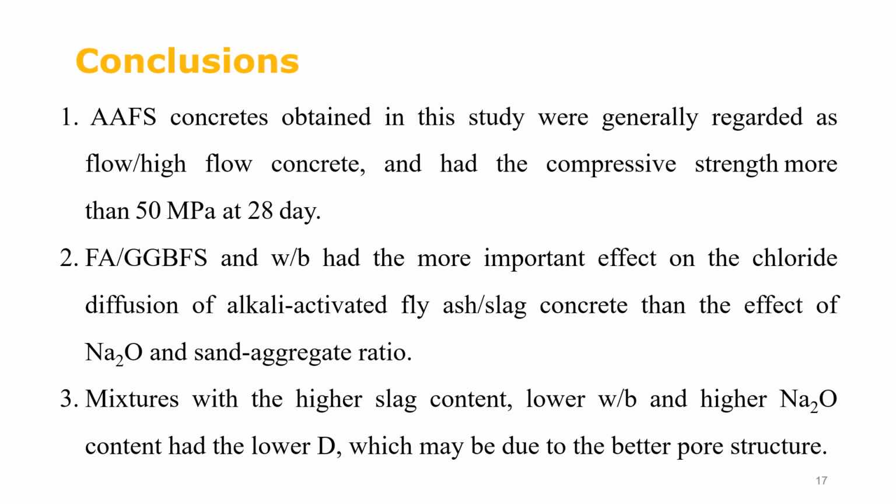After that, compared with alkali content and sand aggregate ratio, the fly ash slag ratio and water-to-binder ratio had more effect on chloride diffusion of alkali-activated fly ash slag concrete. Finally, mixtures with higher slag content, lower water-to-binder ratio, and higher alkali content had a lower D, which may be due to the better pore